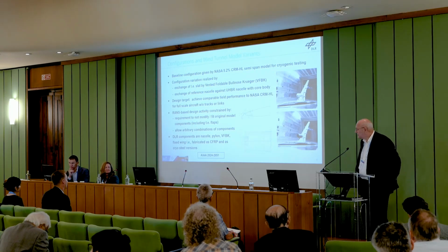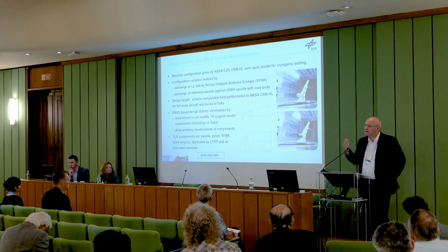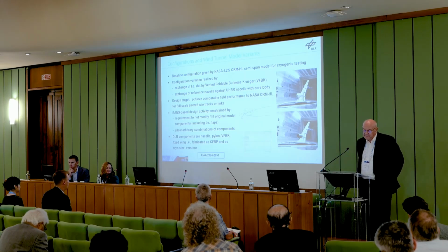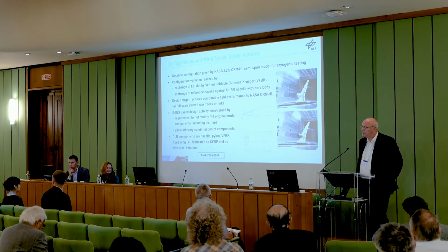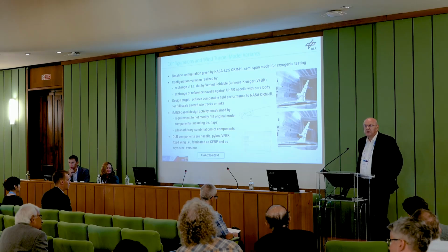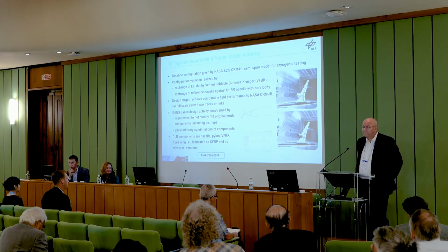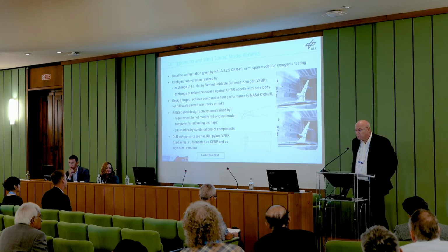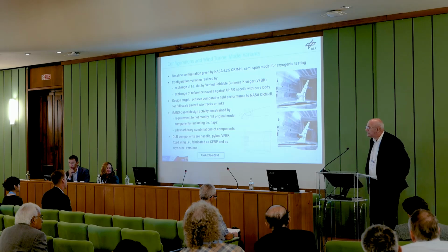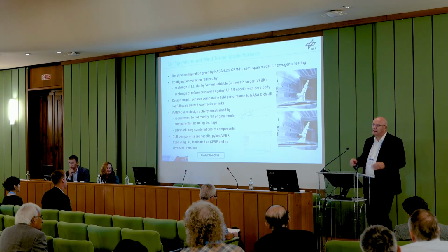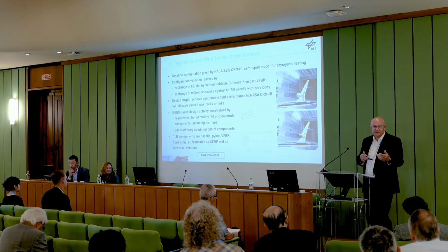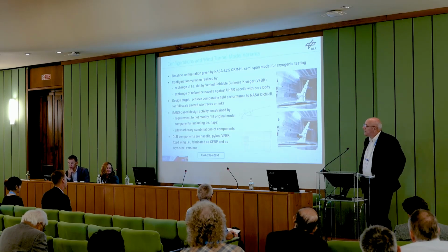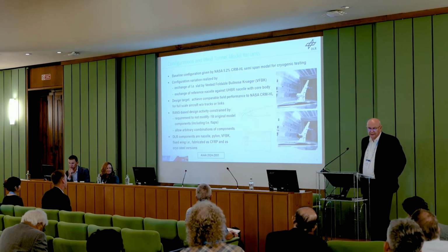For instance, the trailing edge flap wasn't touched. So you might want to adapt the trailing edge flap if you design a Krueger. That wasn't possible, but that shouldn't be a big problem because the intention of the design was not performance optimization, but to create validation data. And the second consideration was to allow an arbitrary change of the components, which we did. That means we exchanged the slat and kept the NASA nacelle and also took the UHBR nacelle and tested it with the NASA slat.